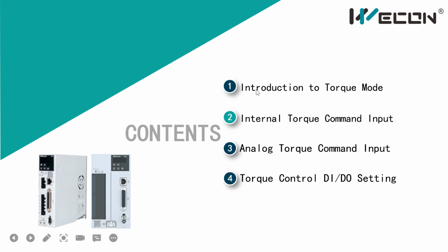I will first introduce what the torque mode is, and then introduce two torque sources: internal command input and analog command input. Last, I will introduce some DI and DO settings of torque control.